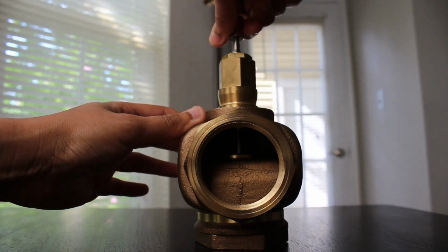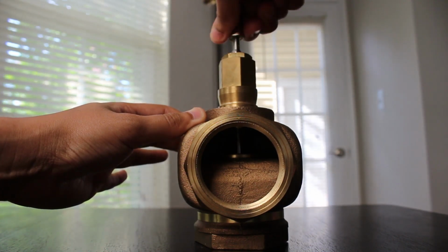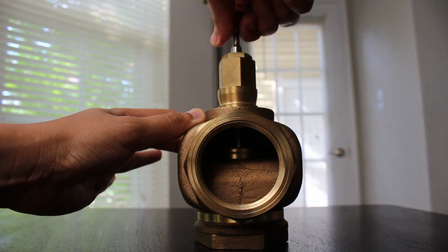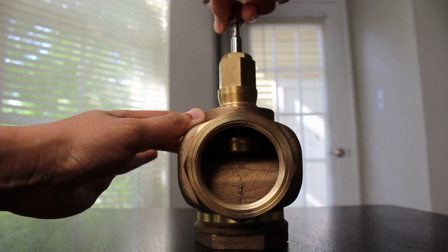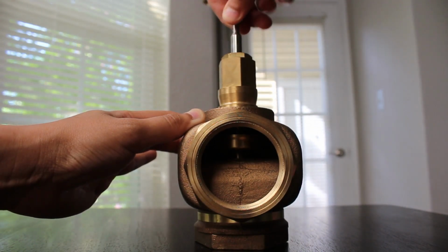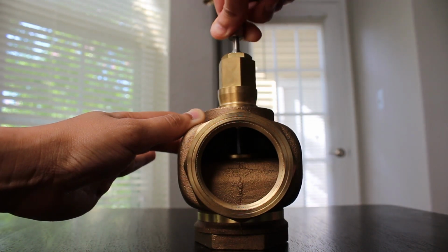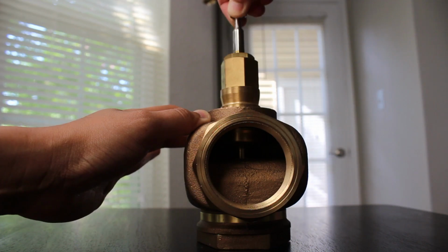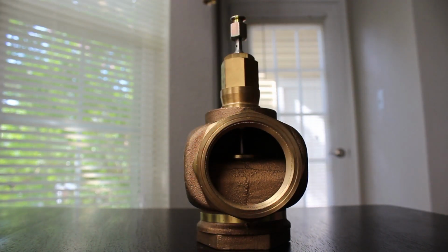As explained in the video earlier, globe valves have plugs which you can see inside the valve which I'm turning right now. So the actuator holds onto it, turns 90 degrees, which will bring the plug up, which gives you the flow. Once it rotates clockwise again, it pushes the plug down, which restricts the flow. This is how the globe valves work with actuators.